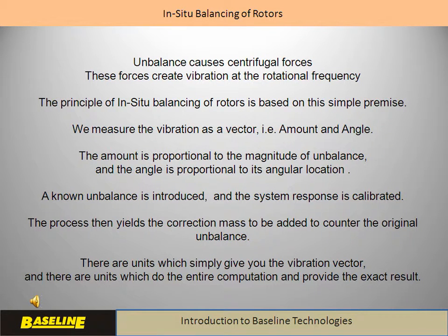Unbalance causes centrifugal forces in a machine. These forces create vibration at the rotational frequency. The principle of in situ balancing of rotors is based on this simple premise. We measure the vibration as a vector, that is, amount and angle.